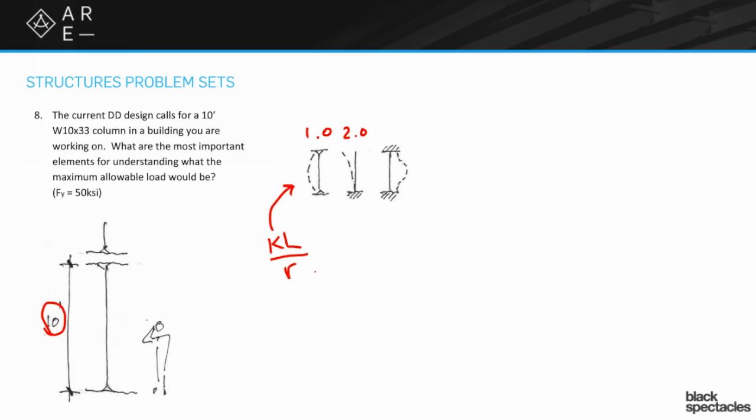One of the ways the column can fail is through buckling, and another way is that the material itself fails, like steel or concrete, just having so much load on it that it fails. But which ones are which, and when do you need to use the formulas for buckling versus the formulas for the capacity and robustness of the material itself? If you just exaggerate it in your head,